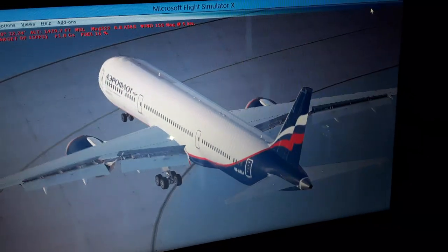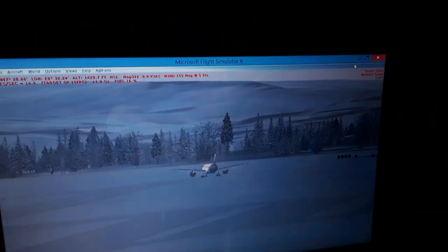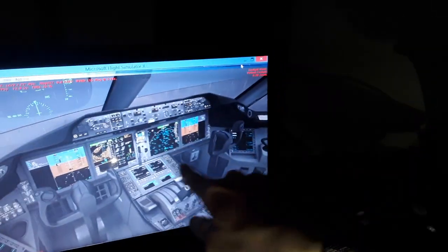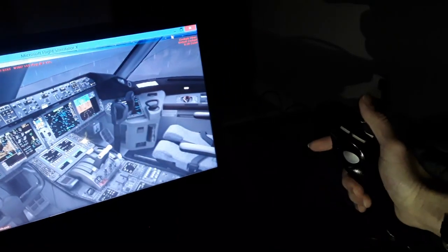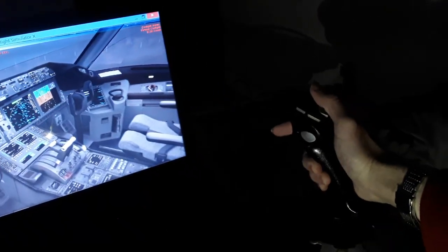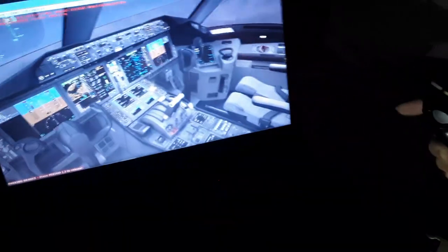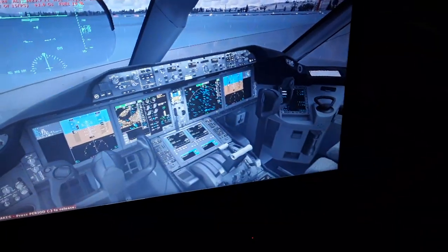The takeoff is the opposite. So this is the rudder pedals here. Both sides, the rudder pedals, both in the Airbus and the Boeing, move together, are interconnected in direct mechanical function. In the Airbus, both sides, the captain and the first officer, are interconnected.